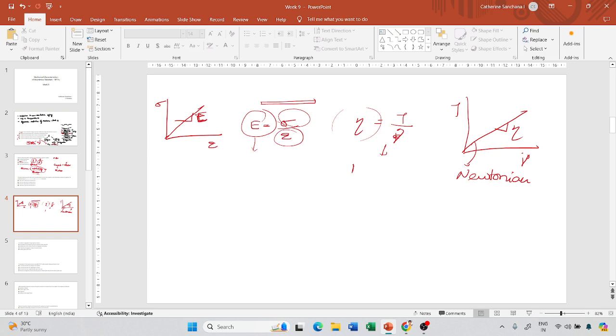So you target for the material to have a Newtonian response. Only then is its viscosity independent of shear rate and it can evenly coat the aggregates. Okay, so that is why we target a Newtonian response for mixing and compaction, mostly for mixing, okay, because it has to coat the aggregates. Now that I explained what a Newtonian behavior is, let us see what a non-Newtonian behavior is.